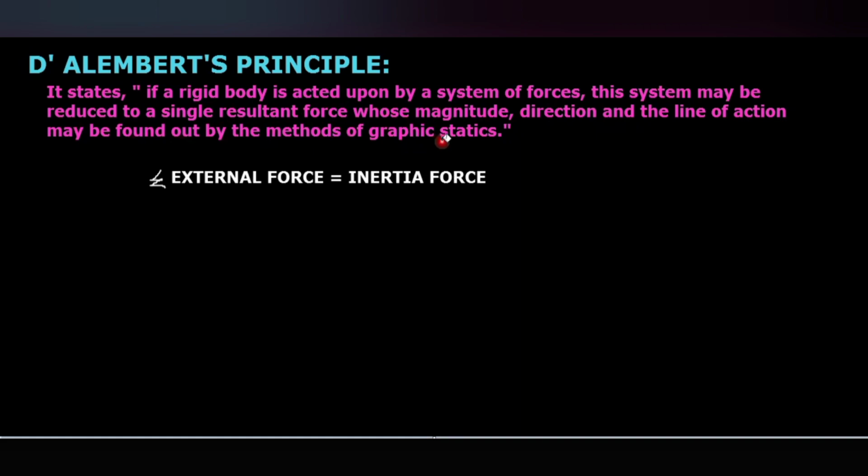Simply, we can say the summation of external forces equals the inertia force. Inertia force numerically equals the product of mass and acceleration, and this inertia force will always act opposite to the direction of motion.